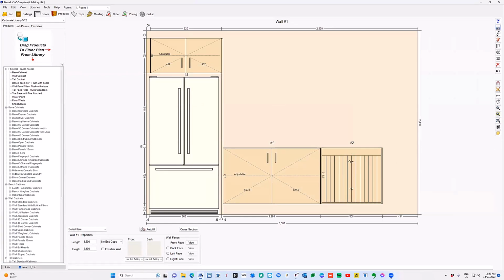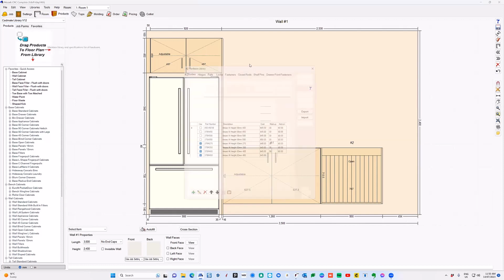So Kevin said, I assemble cabinets with finished ends using dados and pocket screws. To get the dado breaks for the pocket screws, I need to use another fastener. Is Mozaik going to add dado breaks for pocket screws? The other thing is that pocket screws are limited to just 4. Well, pretty much all inserts, all joint templates are limited to 4.